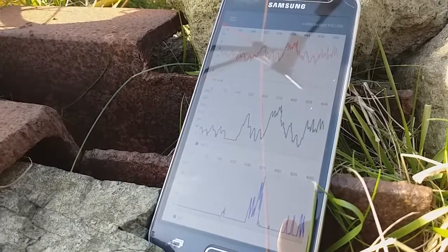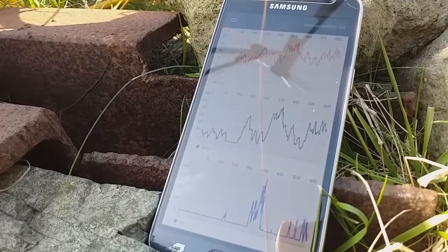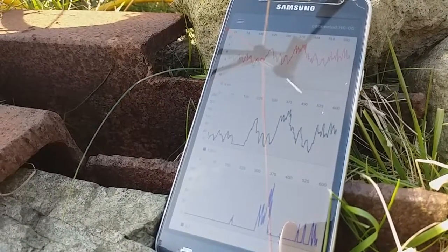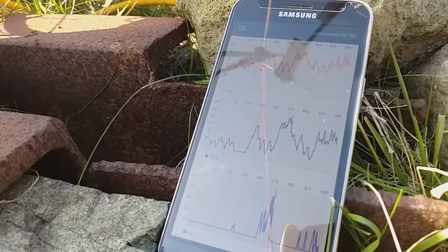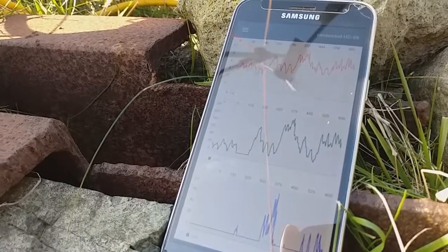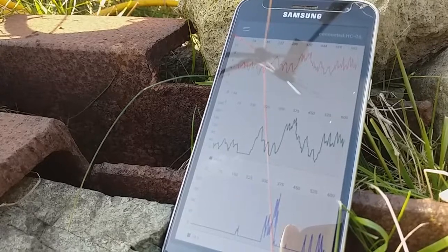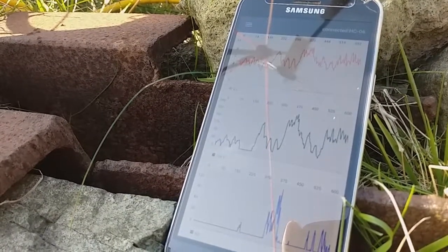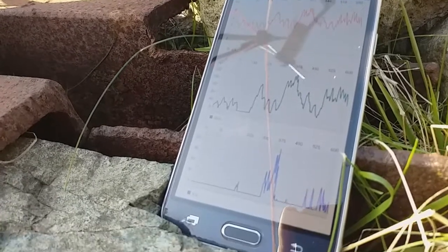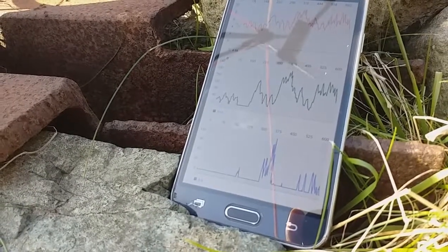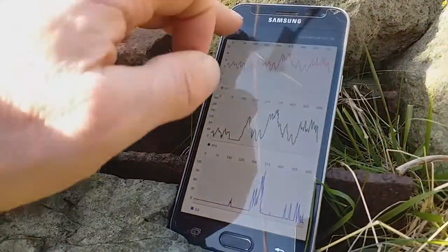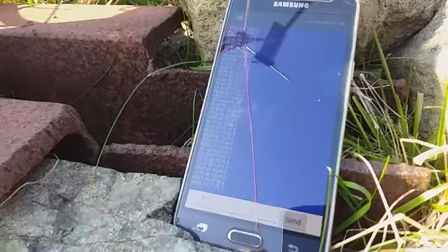We've also got the code sorted, so the wind speed, the top graph, and the turbine RPM, the middle one, are now able to read right down to very low wind speed, and the RPM goes down to about 15 without any silly spikes where it goes up to its maximum. And at the bottom there is the current. We've also got voltage, and you can see that on the data here.